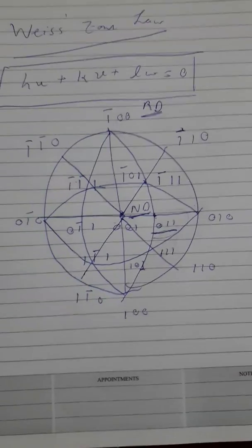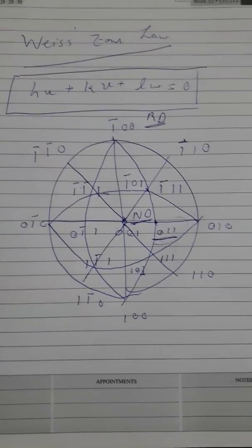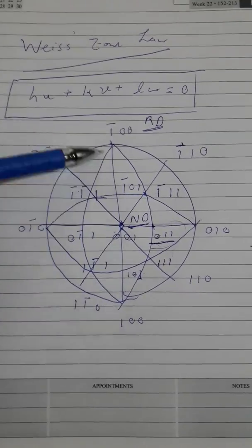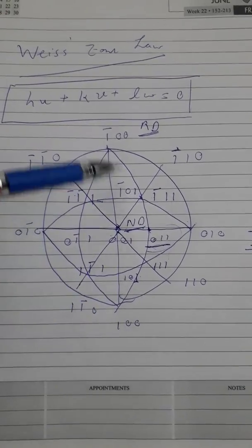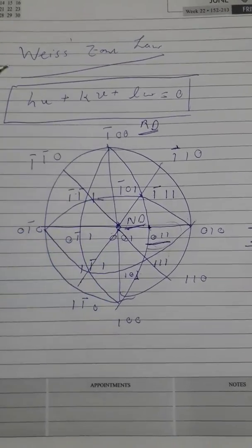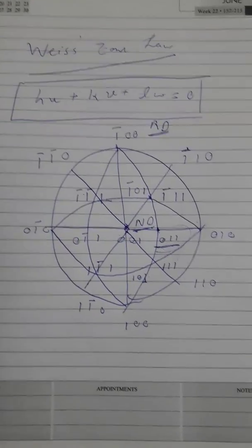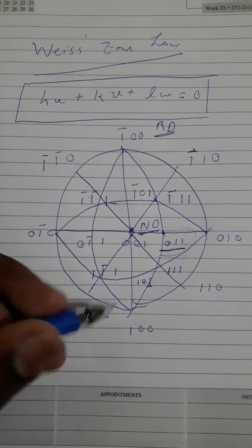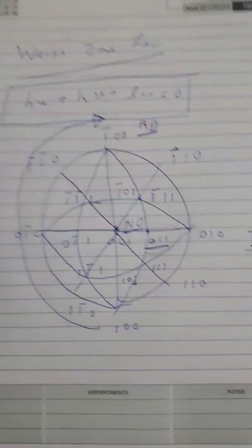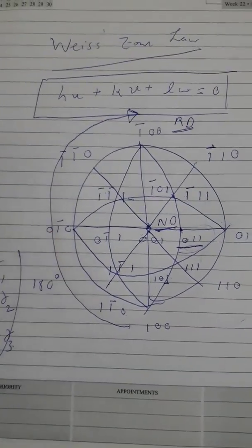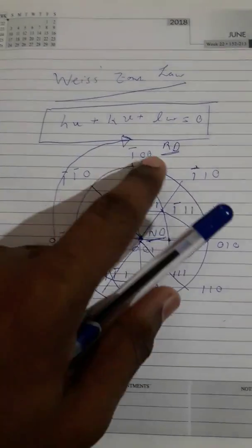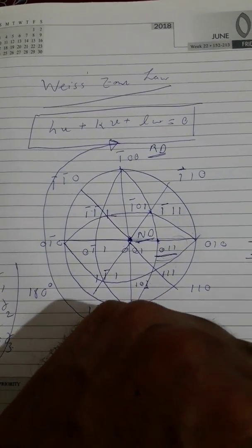But for the sake of learning, suppose we are given other crystal systems like tetragonal. There this problem may not arise again, because bar 1 0 0 and 1 0 0 are again equivalent through symmetry in tetragonal. But 0 0 1 and 0 1 0 are never equivalent. So what we need to do is rotate this 1 0 0 clockwise, or anti-clockwise, whatever we wish, by about 180 degrees about 0 0 1, so that ultimately we have 1 0 0 at the top. I will show that on the next page itself.